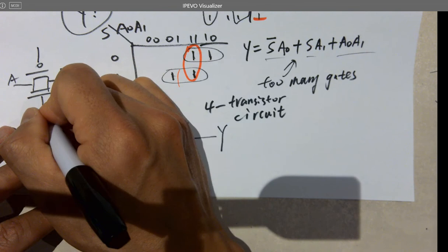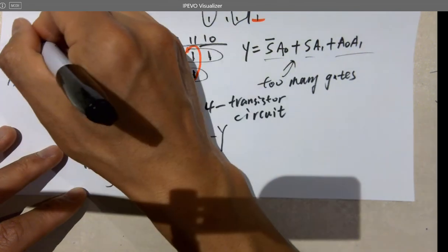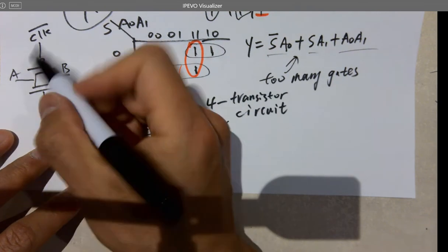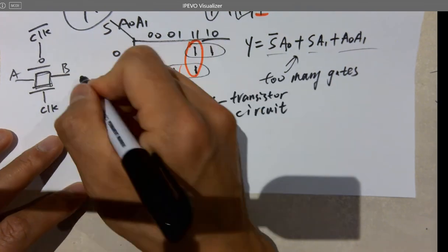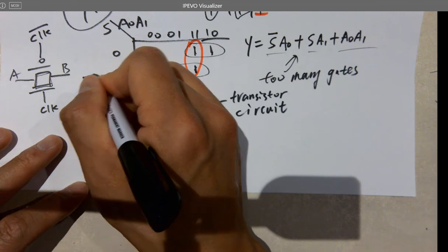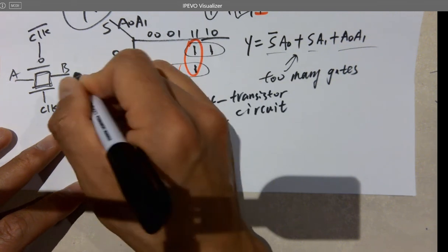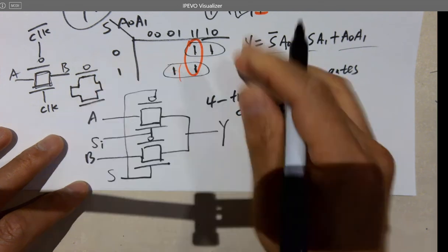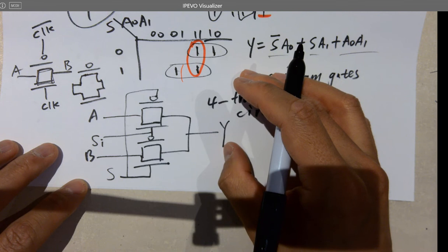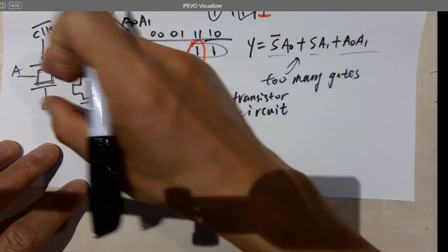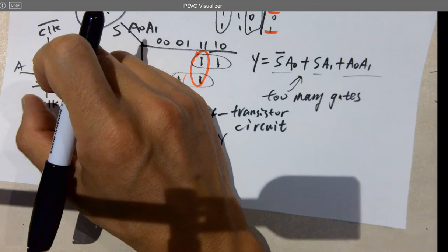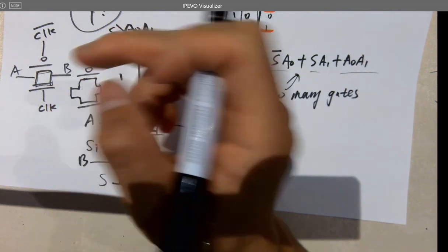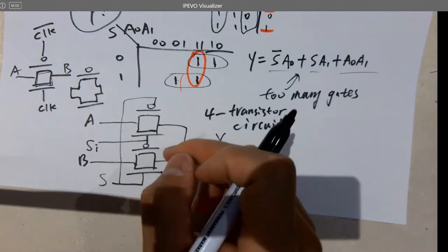And when you have a clock here, and you invert the clock here, to pass A to B, this box here is just one PMOS on the top and one NMOS at the bottom, like this. The reason we need two devices is because PMOS is good at passing ones and NMOS is good at passing zeros. It's better to have both of them instead of just one.